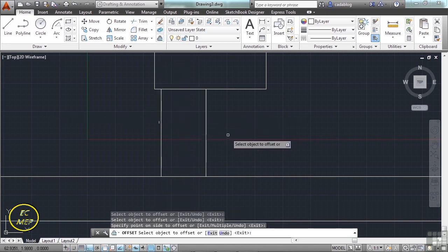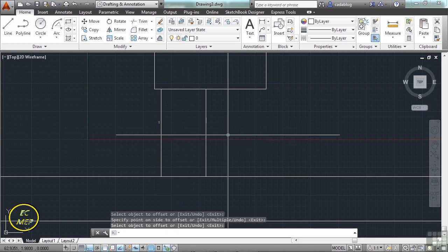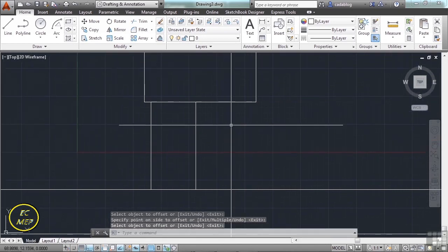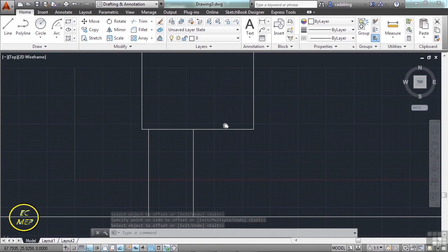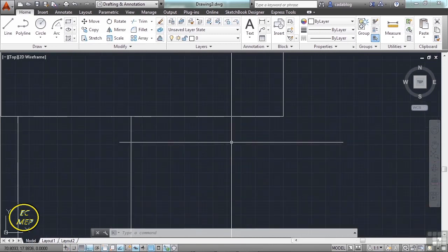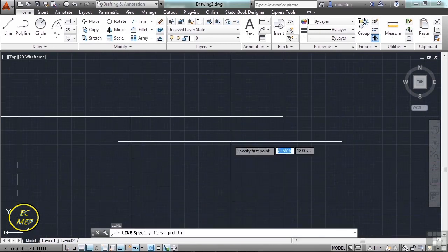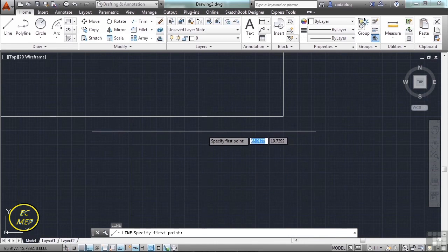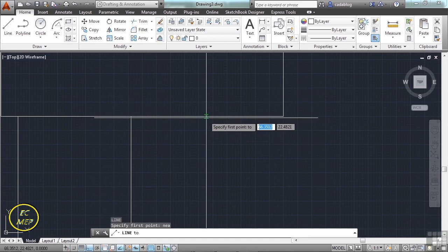Select the line and left click, and there you go. Press enter. Now let's draw a door. Most homes have a door, and we'll draw it just so that the landscape architect knows where it is. Start your line command again. Type in NEA for the nearest O-snap, or use the shift right click to bring up your shortcut window. Click somewhere on the house here.